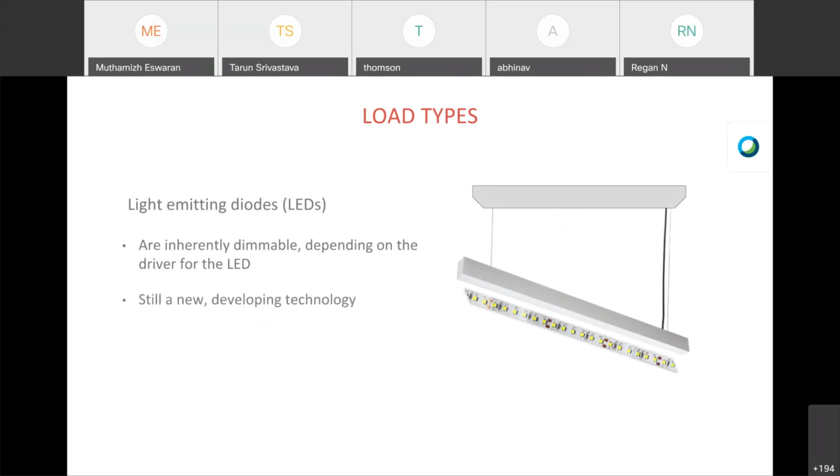And on the LEDs, you might see a lot of issues, right? Dimming range issues, or maybe the dead travel, or maybe it dims only from a certain percentage. It is very rare to see an LED which can dim from 0 to 100. Some LEDs can dim fine from 30% to 60%, and then it goes to 0 or 100%, right? So this becomes more of a trouble.